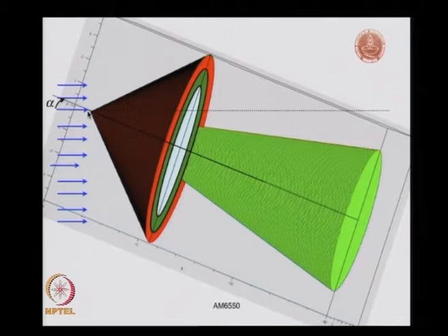If you look at this dotted line, you can see that the symmetry is lost. We will not have flow coming in here, distributing equally in all directions and moving along the surface of the cone. We are not going to have that. Previously we had straight streamlines coming in, deflecting and going past the shock structure. Now these are going to be curved, not straight streamlines.